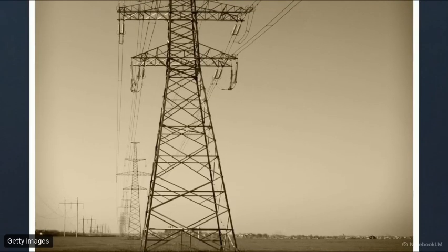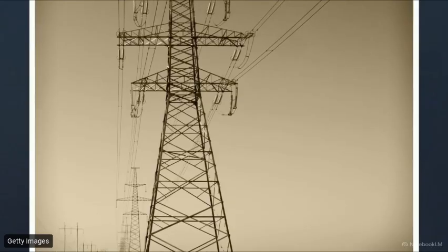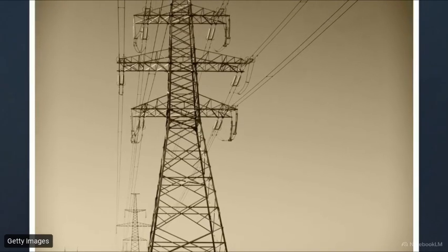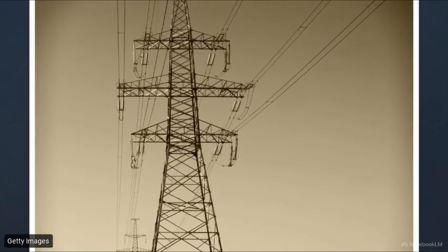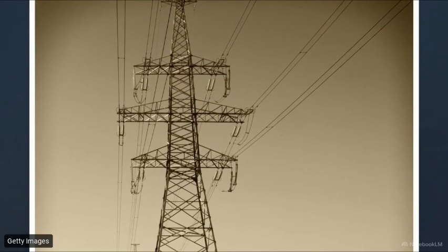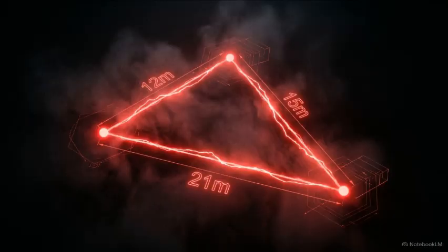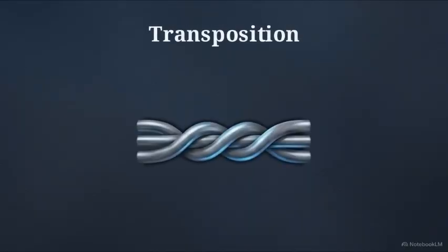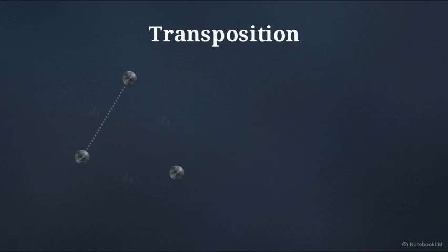Look closely at this real-world lattice tower. Standard three-phase grids carry 3 active wires, and the support arms suspend them at physically unequal distances. This asymmetric spacing breaks our basic math. It creates unequal capacitance between the wires, generating an unbalanced reactive power across the phases. The solution is transposition. Engineers physically rotate the wires to average out unequal distances.